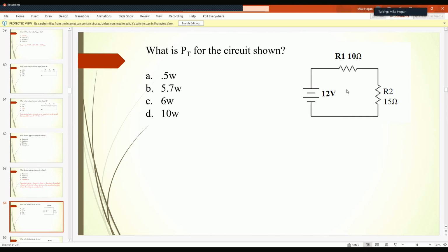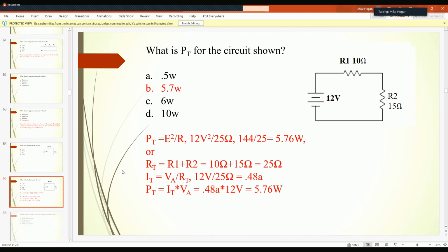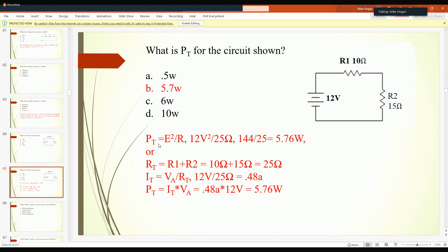Yeah, a couple steps I have to take there, but I can always use power is equal to current times voltage and Ohm's law to figure out what my current is. Those two steps will never do you wrong, right? So there we have power total. I had the voltage squared divided by R. That will work.